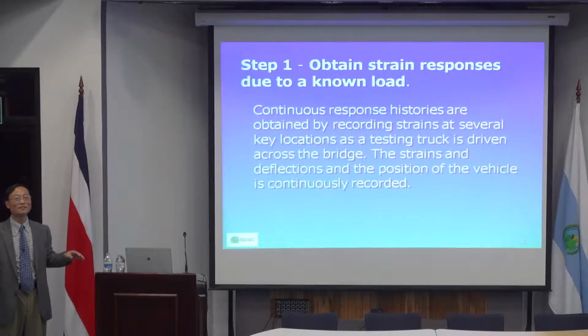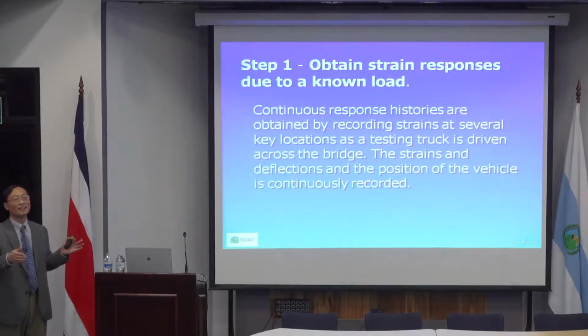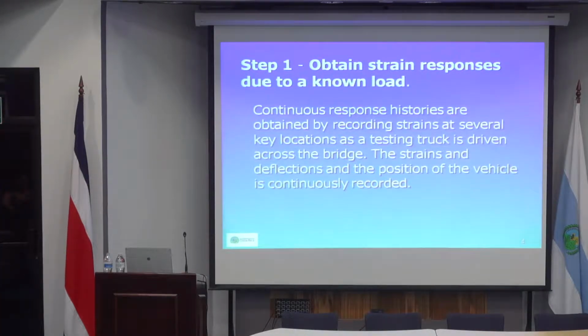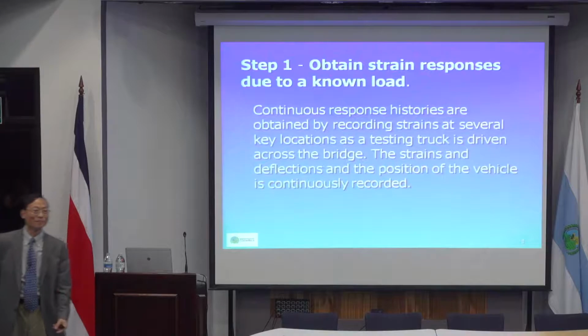Typically when you do the design calculation, if I simplify, if it's a two-lane bridge, you just assume how far the truck can go to one side of the arch. Then you put the truck as close to the right side arch, and you assume one arch is simply supported, and the other arch is supported. You say, okay, this reaction is 75%, that reaction 25%. Then you just say that arch should be designed for 75% of that load.